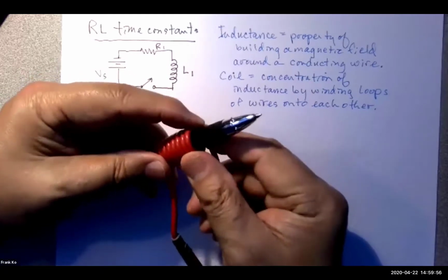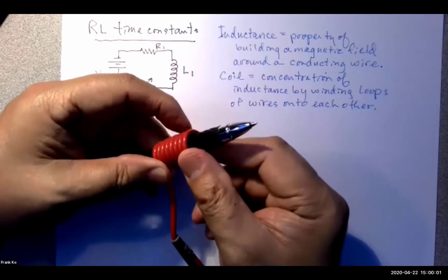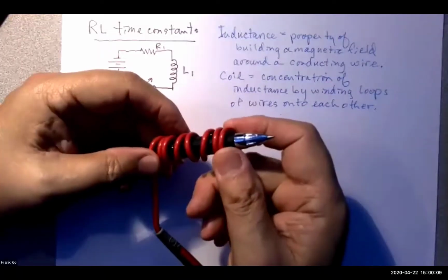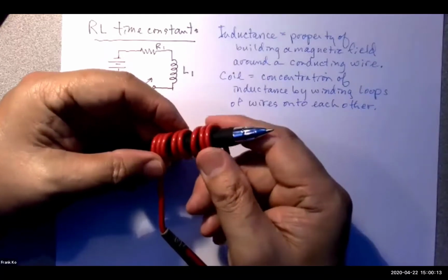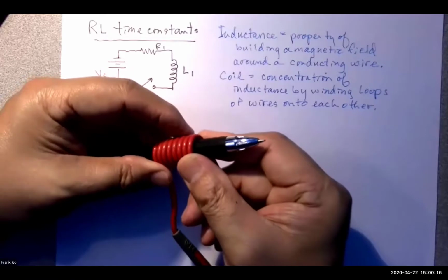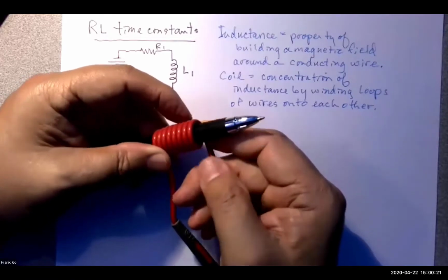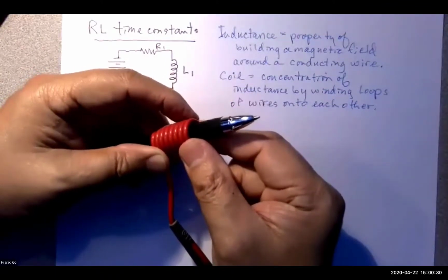So two factors we've discussed so far that affect inductance. One would be what? Question goes to Kyle. What is one factor that affects inductance? How close the coils are together? How close the coils are together is one. So if I pack them up, they're really close, I will increase inductance. If I space them out, I will have less inductance. What is a second factor that affects inductance? Mr. Cortez. The diameter of the radius of the coils. The diameter of the coil. The radius is half of the diameter. Yeah, right. So the same idea.